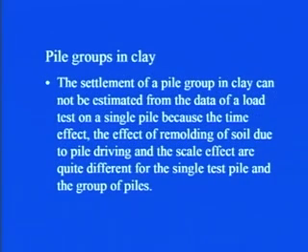Now, pile groups in clay; we were discussing sand so far. So, how can we find out the settlement of a pile group in clay? The settlement of a pile group in clay cannot be estimated from the data of a load test on a single pile, because the time effect, the effect of remolding of soil due to pile driving, and the scale effect are quite different for a single test pile and a group of piles.